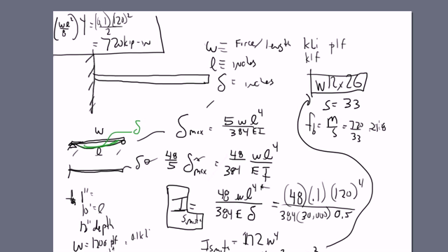And so in this case you see 21.8. That deflection criteria just puts you to the point of being slightly over that 60% of the yield stress. So that turns out to be, selecting a W12 by 26 will get you that half-inch deflection. If that's, I'm sorry, we're looking at a 1-inch deflection here. I'm sorry, we did a half-inch deflection here. So that's going back to not the deflection, we used a half-inch.